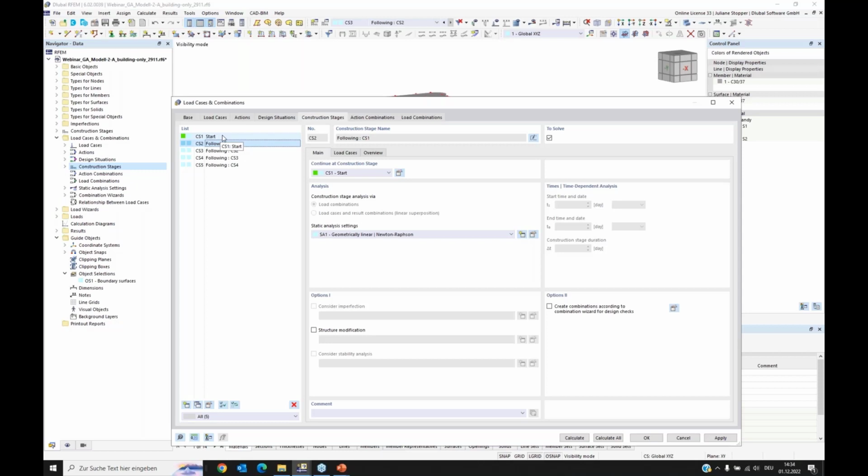But I don't want to see these displacements in my results. I want that when the construction of the building starts, this is my 0 point for the displacements. Therefore, I reset the displacements of the geostatic stress state, and I will do this in the second stage.